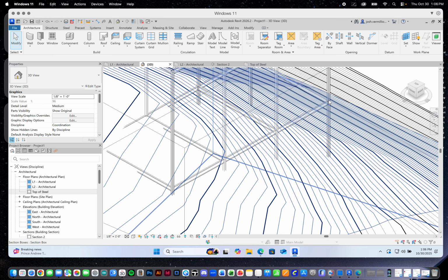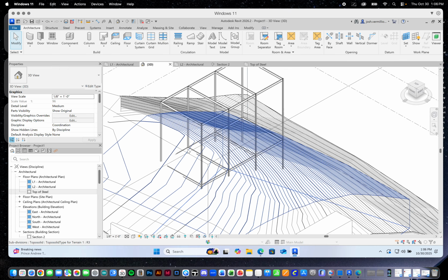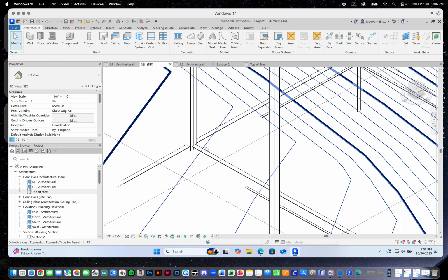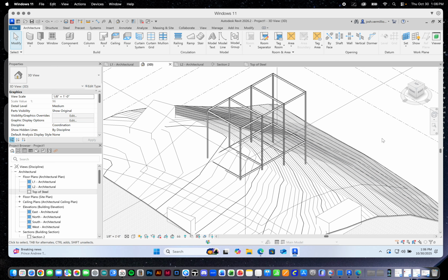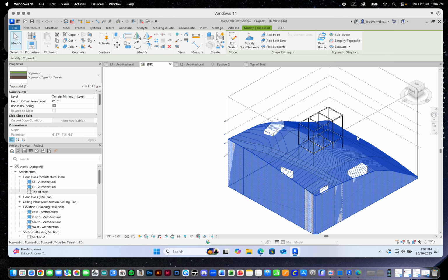Another thing I need to do, unfortunately, is that Revit's not going to remember and keep those settings that I wanted. I need to bring the ends of these beams and just reset their reference to the webbing of the columns again. So one of the things I'm going to do really quickly: right now the site solid is sort of getting in our way. I'm going to go ahead and select it. It's highlighted blue now. And down here in these sunglasses, I can temporarily hide and isolate things. So I can click that and then select hide elements.